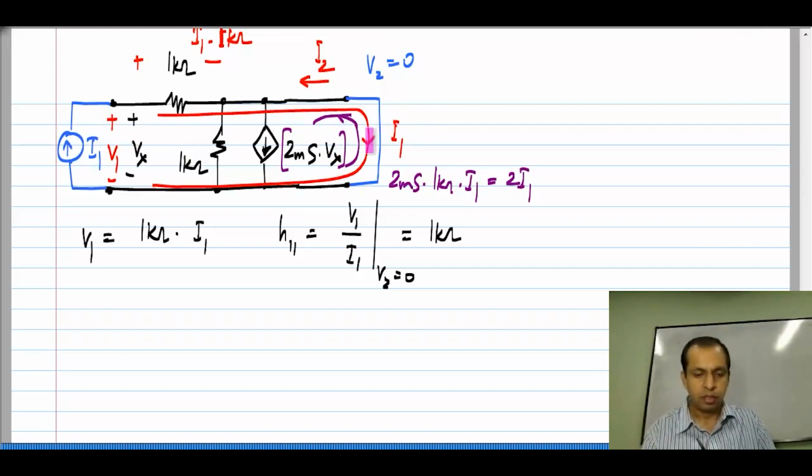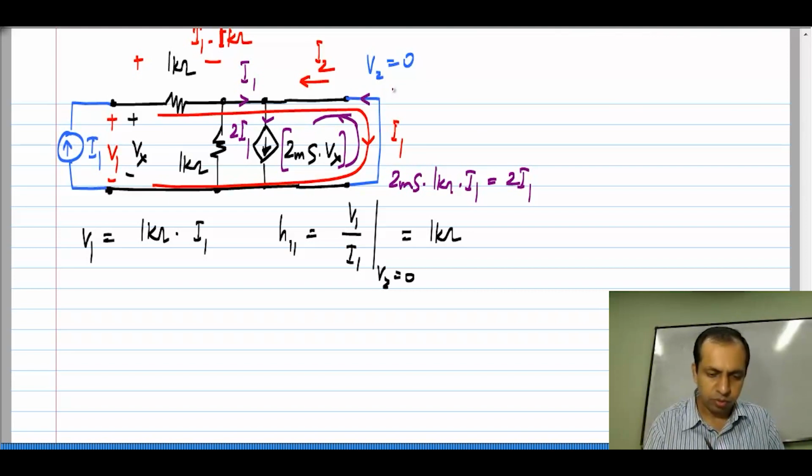Okay. So, the actual current that is flowing in this short circuit, the total current, I just showed this I1 over there, it is not the current flowing here. The actual current flowing there is the sum of I1 which is coming from there and 2 I1 which is going there, which is equal to I1 flowing that way.